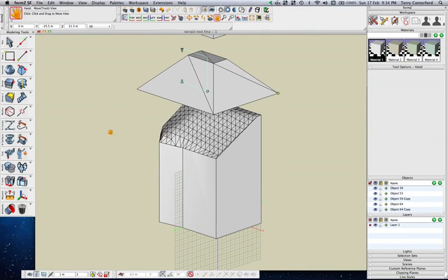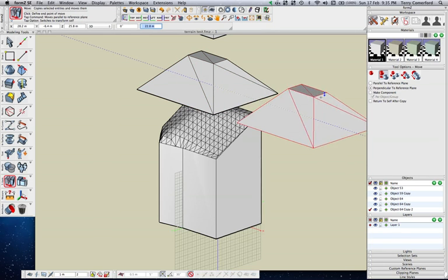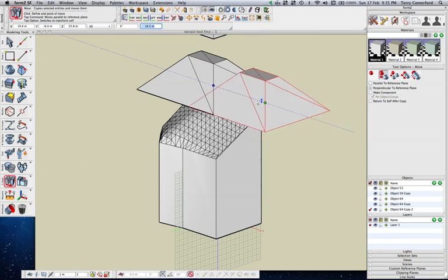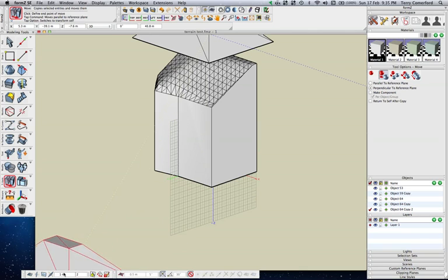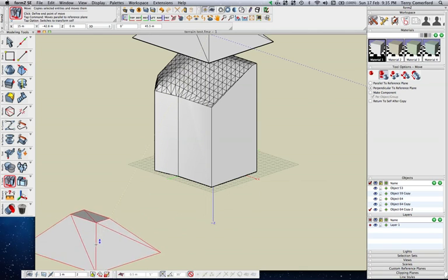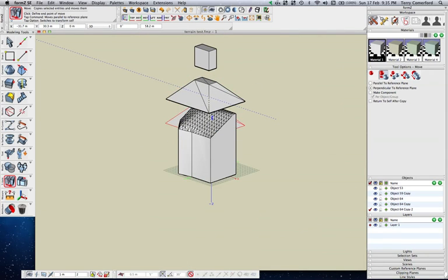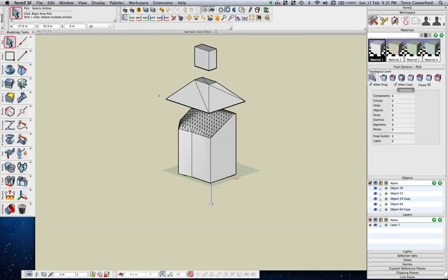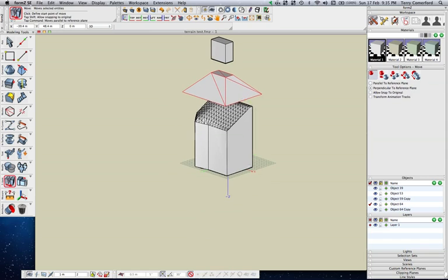Okay, so if I now transform move that object perpendicular to the reference plane, my reference plane for some reason has changed here. That's because I went to a right hand side view, so I'll click back to the top reference plane. This should enable me. I might escape out of that and do that again. So I'll go transform a reference plane, right, perpendicular to the reference plane. Oh no, I don't want to copy, so I'll change back to the first option.